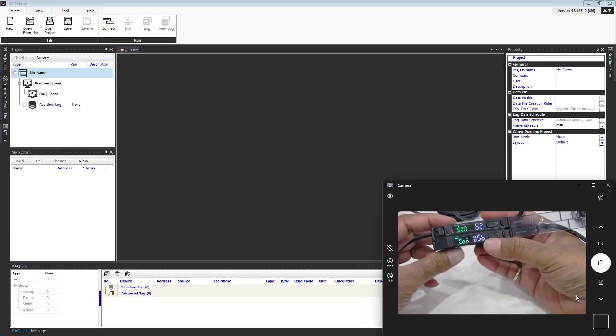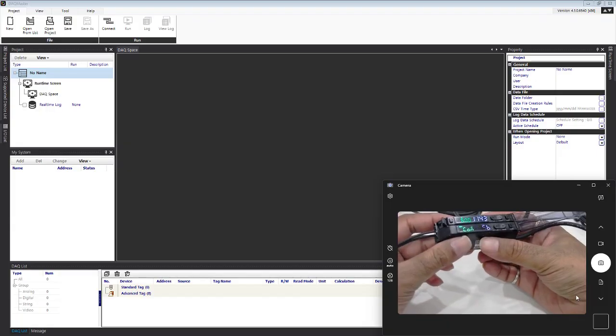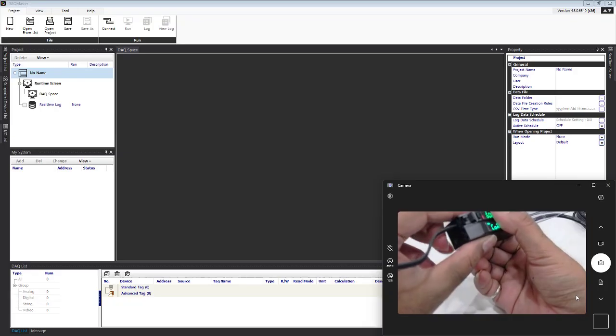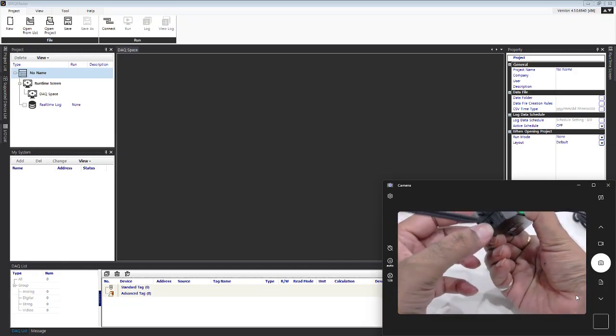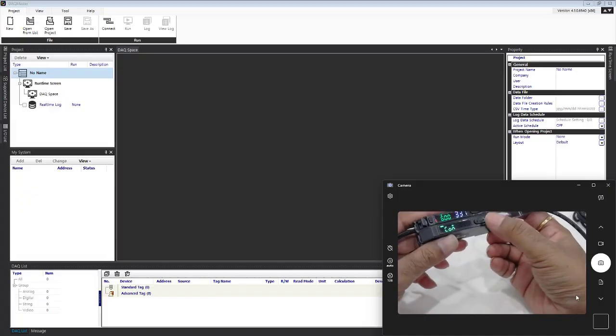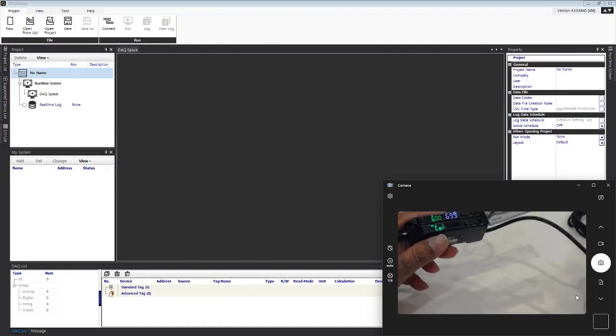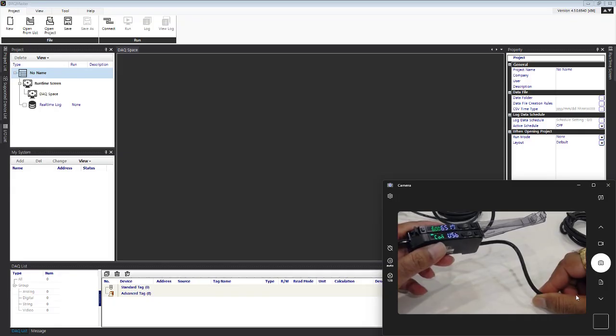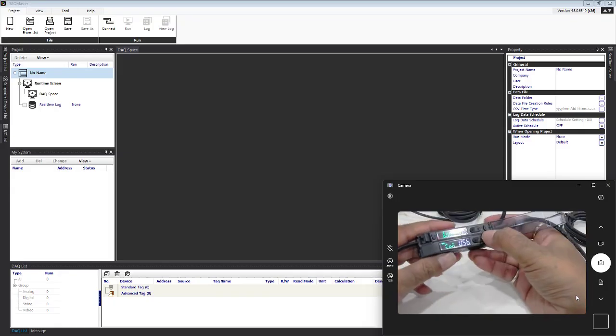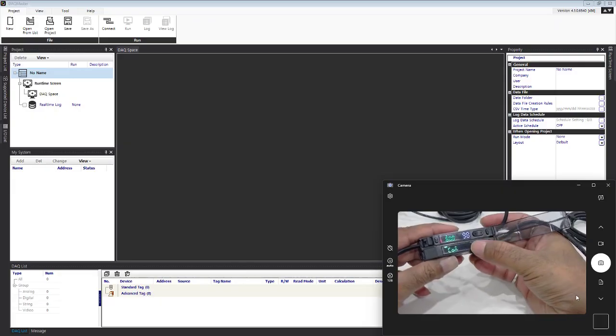With USB communication, it enables the communication through this port, this loader port. So we are communicating with this wire, which is giving us RS485 communication between wires A plus and B minus. So I will change over here from USB to RS485.